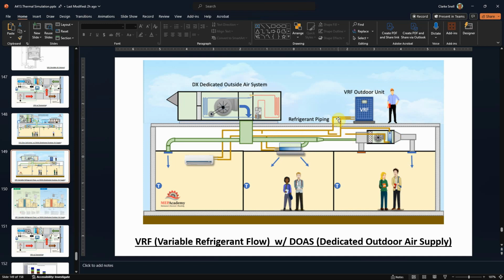So the idea being that we're doing the exact same thing. We're bringing in fresh air. We're attenuating its temperature with this equipment here. And then we're getting the exact temperature we want in the different zones by sending different amounts of this refrigerant to the site. So in other words, there's not a fan here that's changing speed. It's actually just the amount of refrigerant coming that's determining the temperature in the room. All right, that's the summary really quickly.